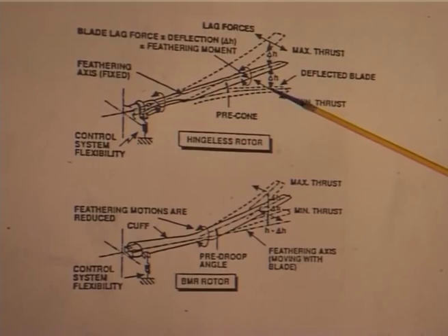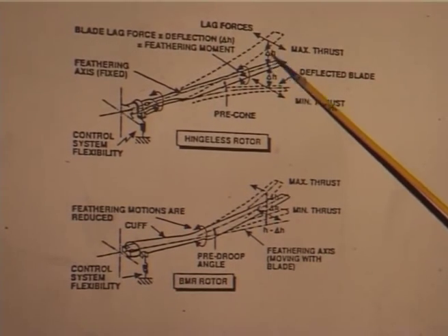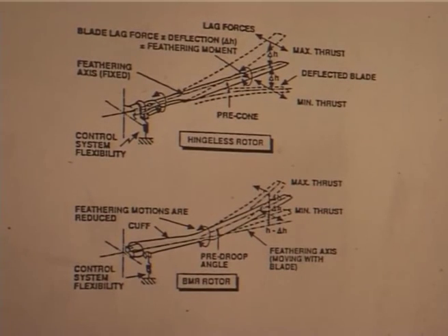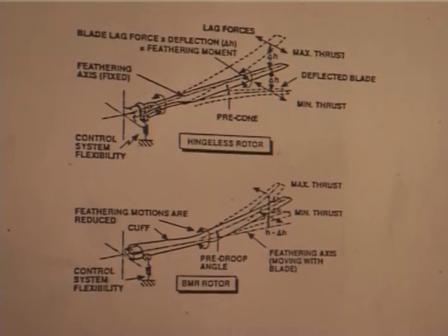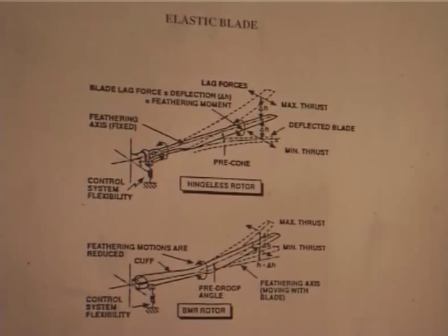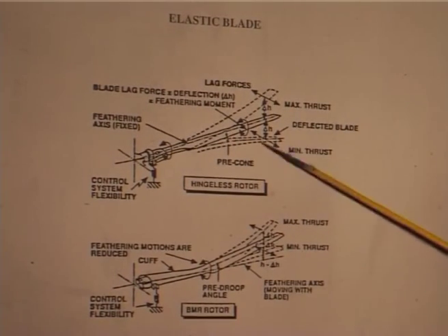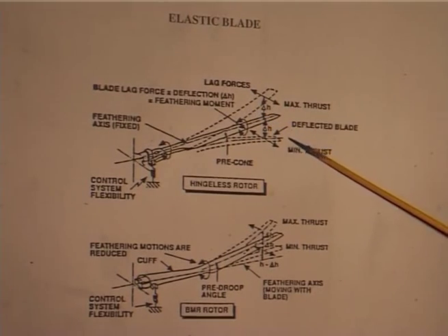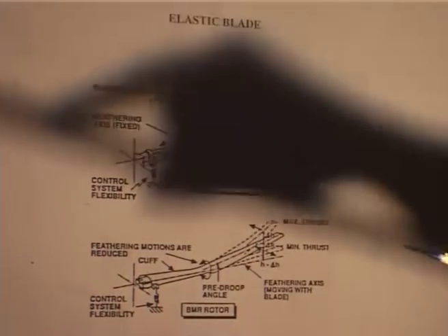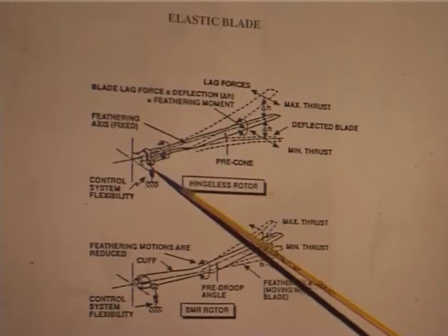Similarly, when the blade goes down, that lead lag force will give a pitching moment. That depends on how much it has flapped. So, how much you flap becomes a factor with the lead lag force, that is the drag force, in changing the pitch angle. Similarly, how much the blade has gone back and how much is the lift, that will give a pitching. This is an elastic blade, that is why it will give.